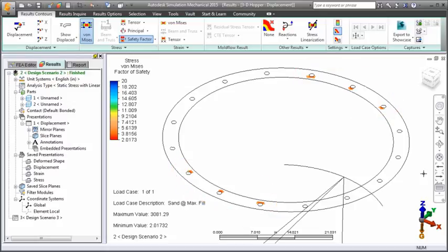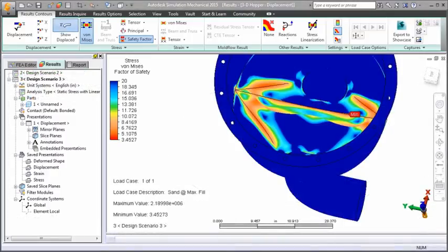On the other hand, you may make an engineering judgment that these are local stress exaggerations caused by the fixed constraints applied to the edges of the flange holes. Rerunning the analysis with the entire flange surface supported rather than just the edges of the holes produces this factor of safety plot. The flange is no longer a low safety factor component.